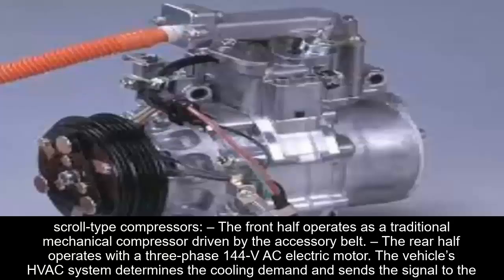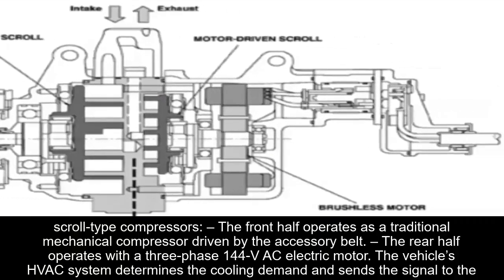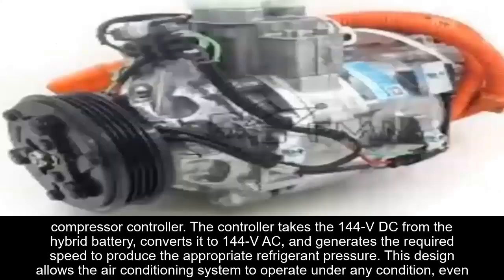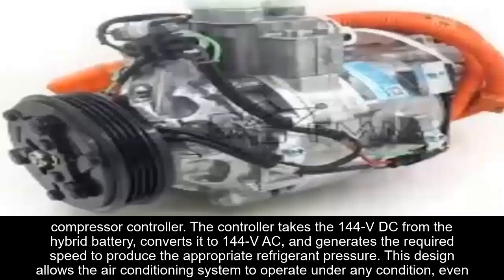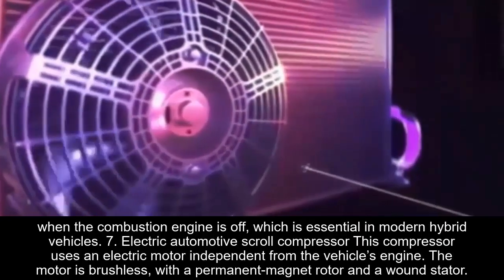The vehicle HVAC system determines the cooling demand and sends the signal to the compressor controller. The controller takes the 144 volts DC from the hybrid battery, converts it to 144 volts AC, and generates the required speed to produce the appropriate refrigerant pressure. This design allows the air conditioning system to operate under any condition, even when the combustion engine is off, which is essential in modern hybrid vehicles.